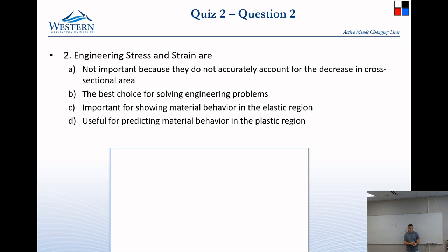You have to measure like the area constantly. Yeah, it's just harder. It takes a much more capable setup to be measuring the cross-sectional area. And in fact, all the systems that do it don't actually measure the cross-sectional area. They have little lasers and they look at the diameter and then they assume that it is deforming uniformly. So there's a lot of assumption going on in that because you have no idea whether it's deforming uniformly or not. That's impossible to say.